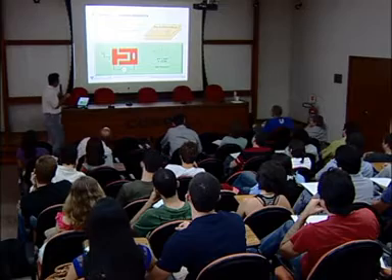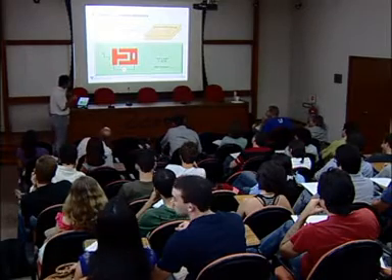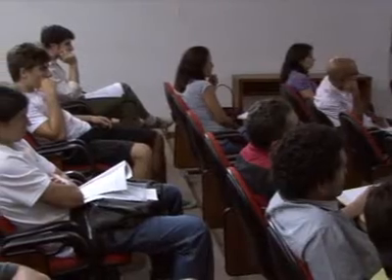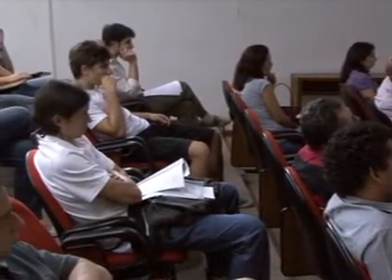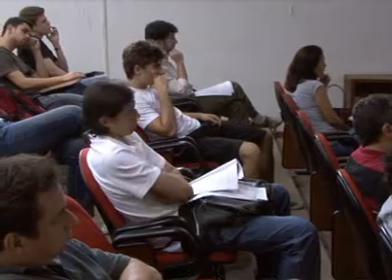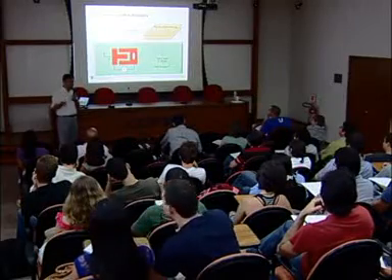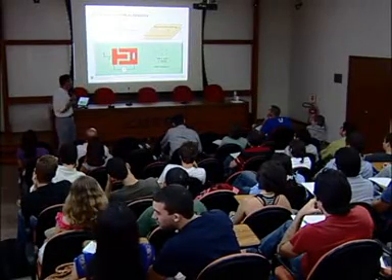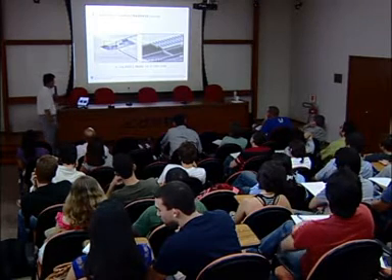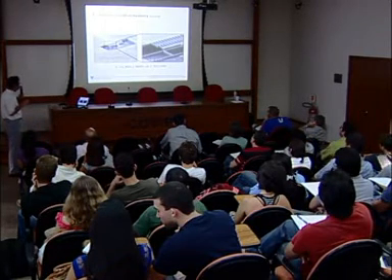So the advantage of MEMS is that we can make many of these. When we make one, we can create about 20 nanonewtons. It's a very small force. But we can make 1,000 or 10,000 or a million of them. Then we can create micronewtons very easily. Okay? So this is a comb drive.